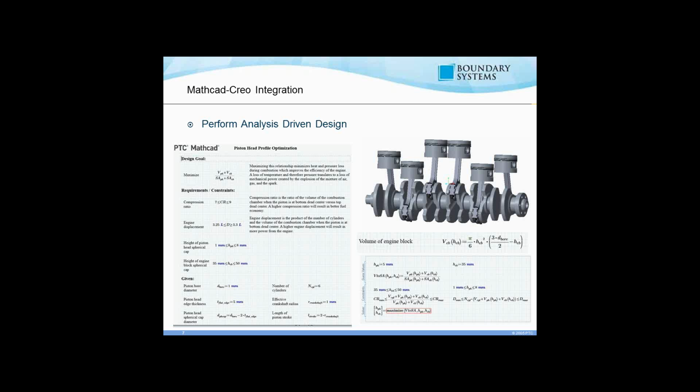Now, not only can you do that, you can also use Mathcad's intelligent solve blocks and logic blocks to do more than just solving equations. And so in the bottom right screenshot, you'll notice there's a maximize text there that's in a red box. With that, you can use Mathcad's intelligent functions to not only solve for a specific value, but also maximize or minimize certain equations, so that way you get the best performance for your particular model.